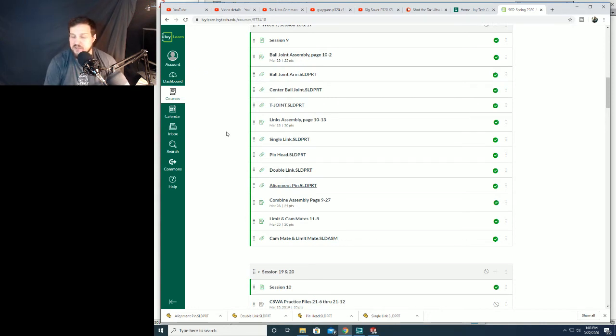Now those mates work very similarly to the way that the relationships work in sketches. With mates, we're going to have mates that are plane on plane, line on line. We're going to have coincident, basically very similar to the relationships that we've dealt with that are in the sketches already.